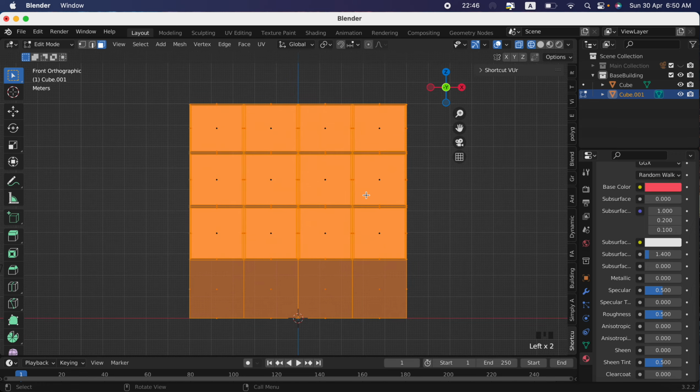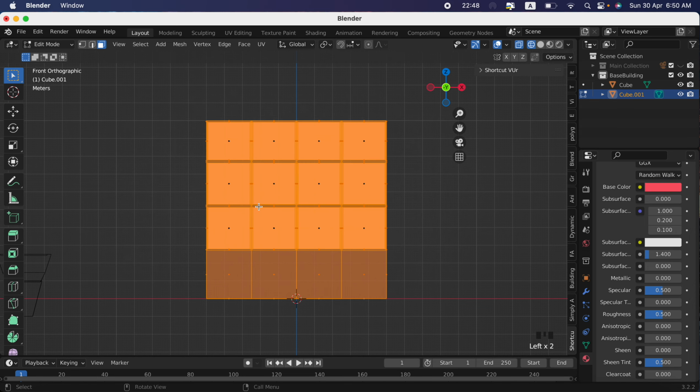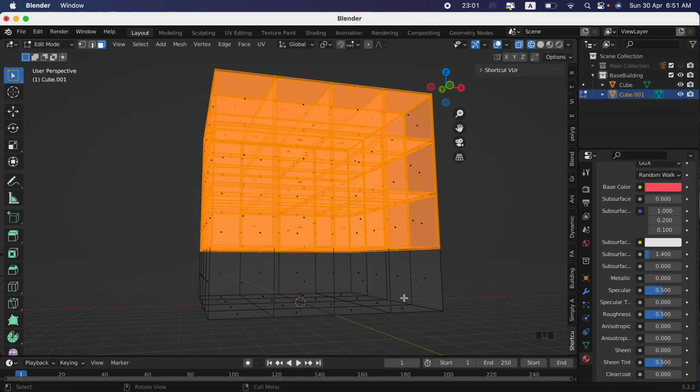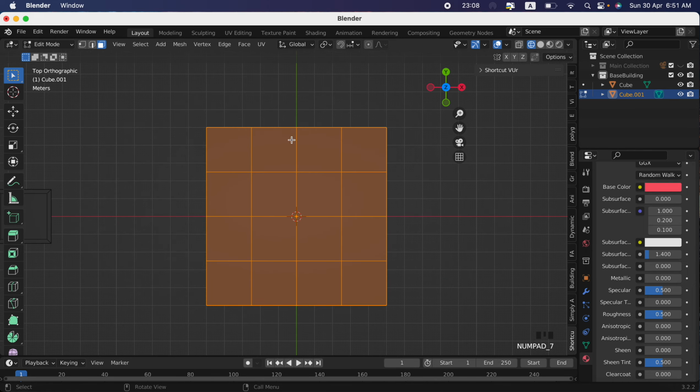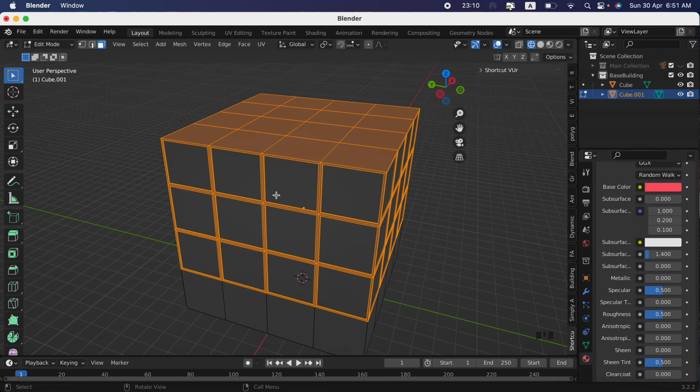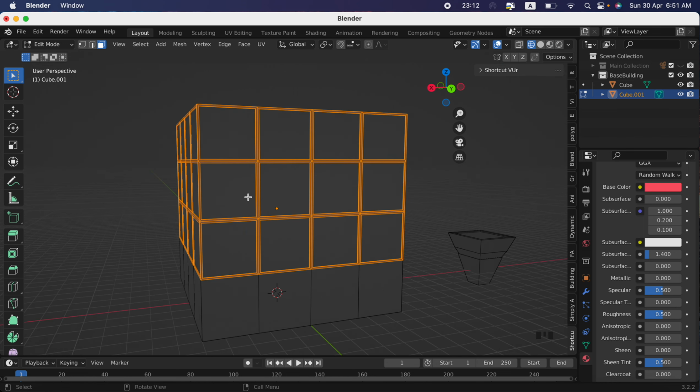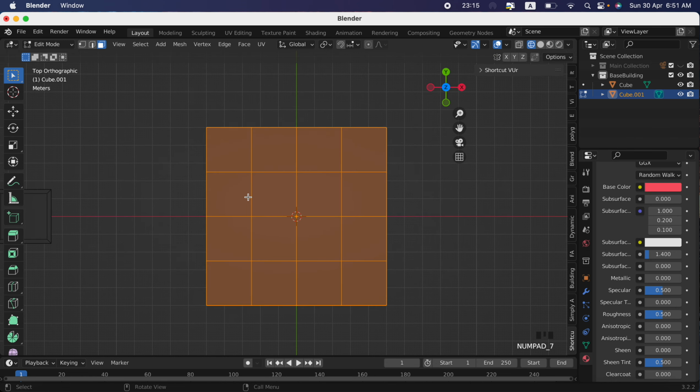What I'll be doing is I press 1, I'll go to wireframe mode, I'll press the B button, and I try to unselect this thing. Alt, see, I have just unselected this thing. I'll turn off X-ray. I press 7. I want to unselect this thing because I have to make the hinges only. Press 7, press B, Alt, select this thing.